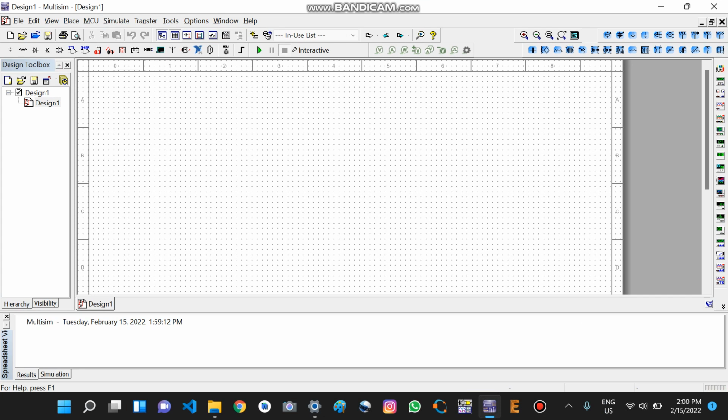and calculating the R value, we get R as 318.3 ohm. We calculated it by using the formula R is equal to 1 by 2 pi fc, where f is 500 hertz and C is 1 microfarad. You get 318.3. Now place a virtual resistor over here. We change the value.